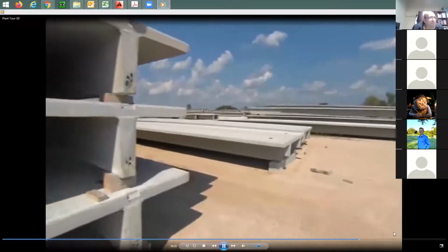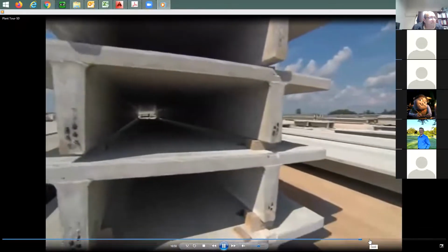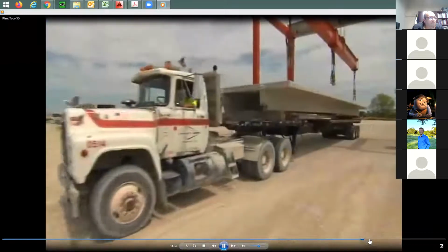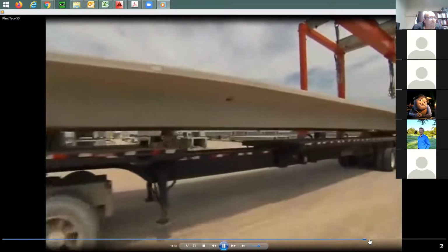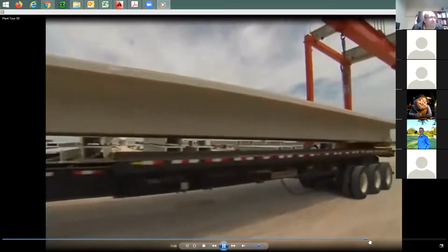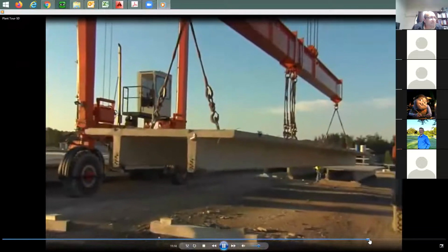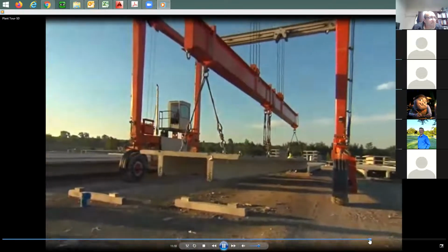After all the work is completed, the double tees are moved into the storage area where they are typically stacked using appropriate dunnage located near the ends. When the job site requires the tee to be shipped, it is loaded on a trailer and transported to the job site. What you have just observed is the process for making one type of pre-stressed product. These other types are made using essentially the same process.